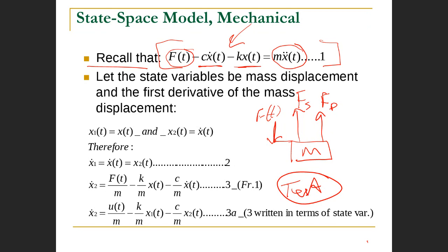Okay. Now, whenever we're going to define a state space model, we need to find the state variables. All right. And I'm reminding you now that the state variables are the smallest set of linearly independent variables, such that if we know the values of these variables along with the system input, we can completely define the system's behavior. Okay, so if we now need to derive a state space model for this system, the first task at hand is to establish the state variables.